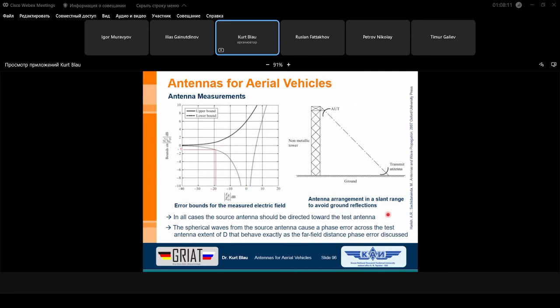It's clear, if the antenna for illumination does not look directly at our antenna under test and shows, for instance, a value in the pattern near a zero or a side lobe, then the dynamic range is not full, meaning we cannot measure in special cases the depth of a zero. We can only see that the measurement receiver goes down into the noise floor.